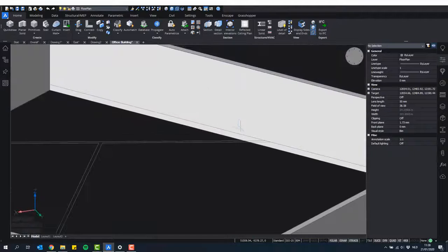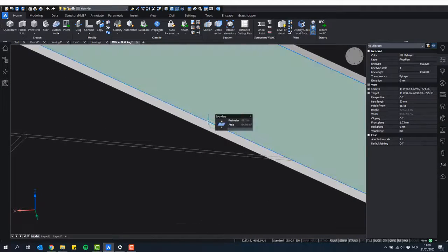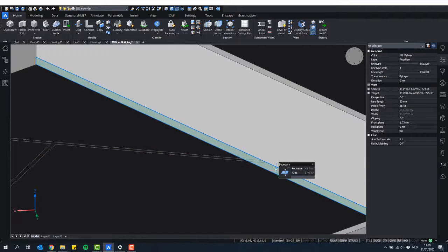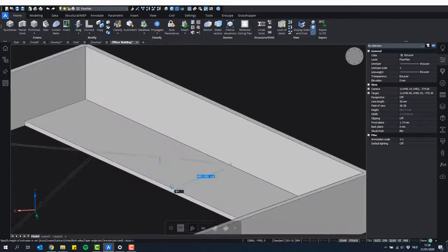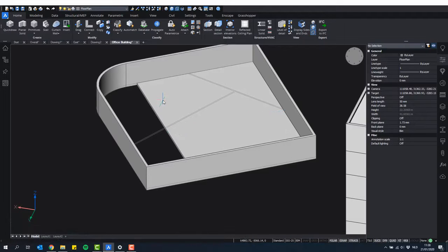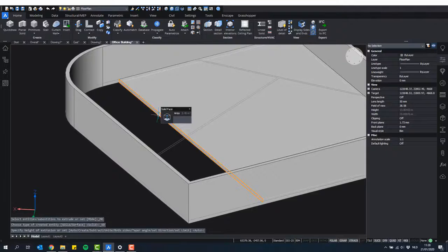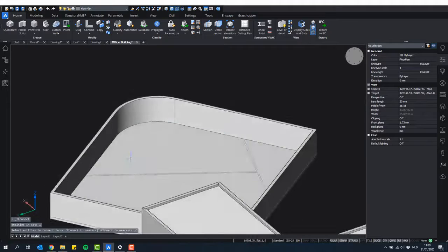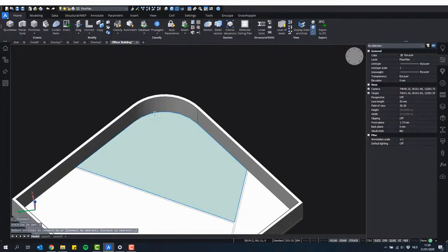The reason I did this is because now you see under this line here at the bottom edge of my wall, now there's a boundary, because this line makes the boundary between the bottom edge of the wall and this line. So I can use this boundary again to create new geometry. For instance, I can create a new floor slab by using solid extrude. I will extrude it to somewhere, let's say over here. Now I can use, again, the connect with nearest tool like before to create the floor slab. Now it nicely fits around this round edge here as well.